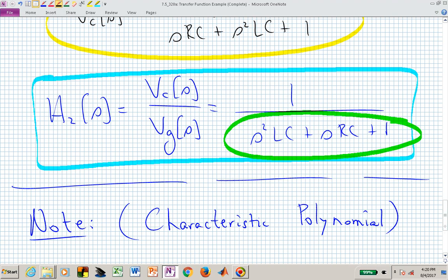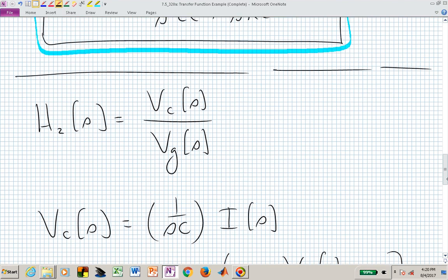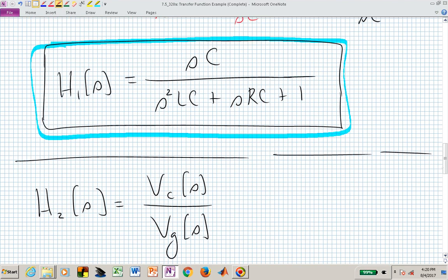So the poles of your transfer function provide you with a lot of insight into how that system or that circuit naturally wants to behave or shake or move. In this case, the system will shake according to the roots of this denominator polynomial, which produce the poles of your system, and that's obviously from this expression going to be connected to the particular values of L, C, and R in that RLC circuit.